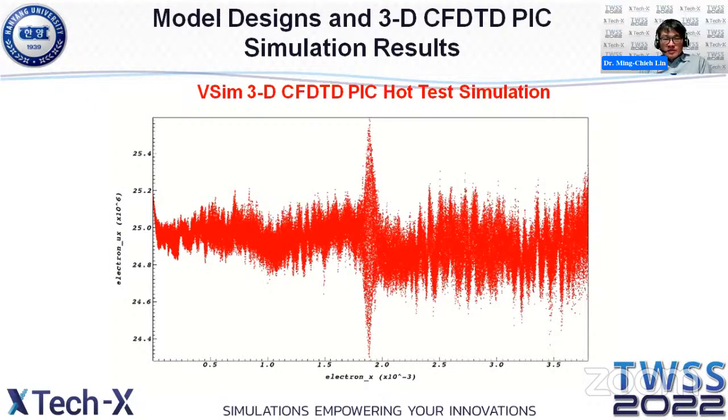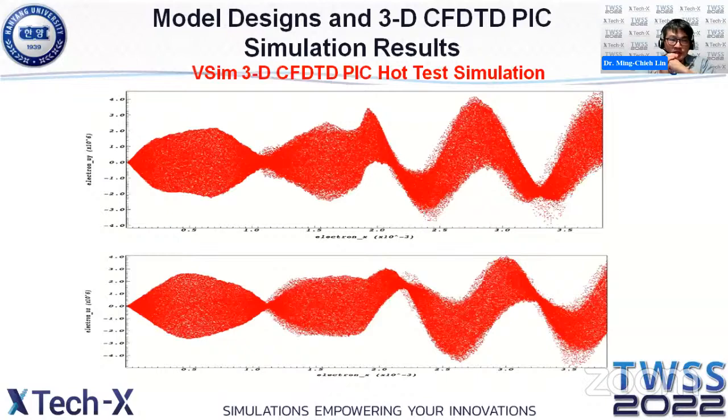First we start with the signal turned on. So we have the terahertz wave excited in the cold-test simulations, and just launch the beam together. You can see this electron beam will be modulated by the terahertz signal we excited. This shows the phase plot in the x direction, ux versus x, which gives you the phase information. In the transverse direction we have uy versus x and uz versus x. So you can see longitudinal bunching and this is transverse bunching. This also demonstrates why we want to use the LSM11 mode, because it's symmetric in the transverse direction. This is very good for a wave generator.